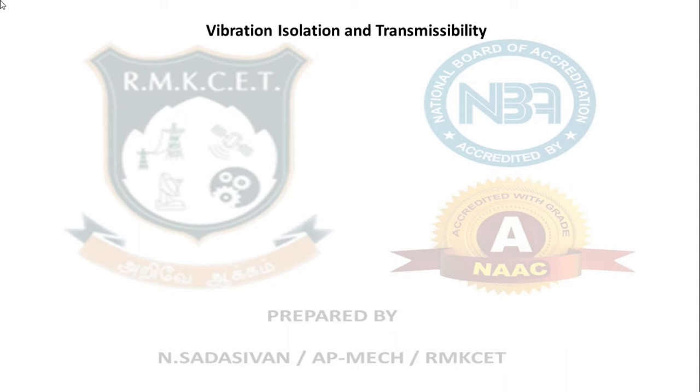Now, this is a single point cutting tool. So, when you are trying to shear away the job, how does the material get removed when you are turning in a lathe? How do the chips form? How does it come out, and how do you get a smooth surface? All those things you have already studied. The material removal occurs on a theoretical shear plane, which is almost 45 degrees to the rake face of your tool. This shear plane keeps traveling in front of the cutting zone, and you are able to create a very fine smooth surface on the material by machining.